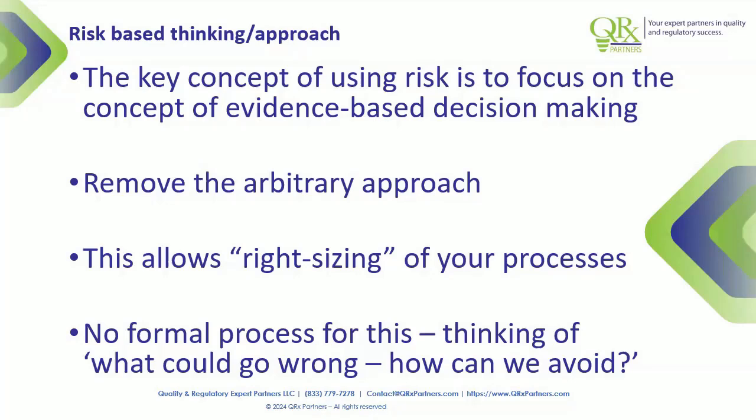The same thing with preventive maintenance. The manufacturer of that piece of equipment has no idea what your use is, right? You do. And so when it's going to have some effect on your product, or at least you should. So you might start with the manufacturer's recommendations, but at some point you should adjust that based on risk, right? When did it actually start producing? When did it have an impact on your product? Now we can adjust the cycle, right? All of these things that are time-based.